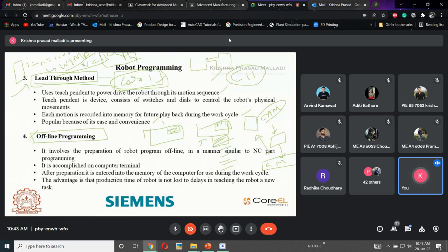I have defined a part like this, a turning application. In virtual manufacturing, I have turned this part with some tools and everything. Once it was done perfectly, I go for post processing, PP. After post processing, this file is converted into G code and M code. Now I will download this file to a pen drive and give it to the CNC controller, and I will run this application. In the CNC machine, I will get this type of part. That is exactly what this CAM application, or post process application, is.